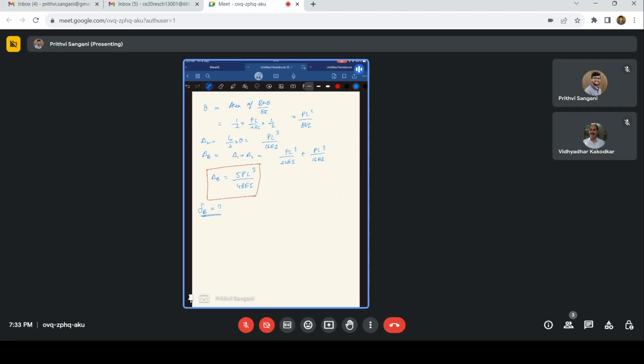The reason why I'm taking unknowns here as 6 is these three unknowns can be found out using the reactions at A. So I have already considered A reactions as unknowns in my external indeterminacy. So to find out the forces, I should actually have only 6 unknowns, which are only these and these, because this I can find out directly.